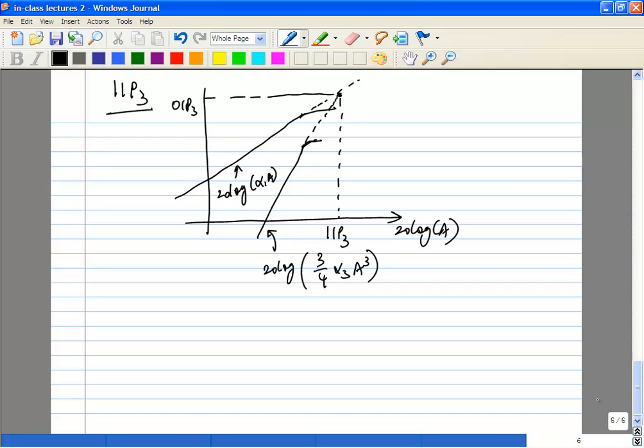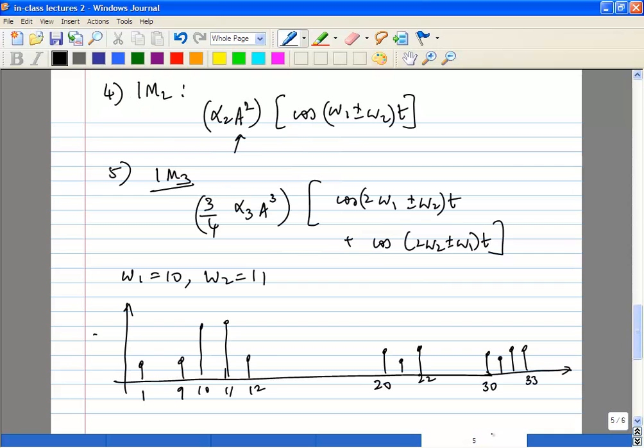You can never really apply an IIP3 power and find out if those two things are equal. What you do is choose 2 points on this and extrapolate. The meeting point is IIP3: the input power is IIP3, the output power is OIP3. This alpha 3 cubed term, is it related to the first harmonic fundamental itself? No, it's actually the third harmonic.